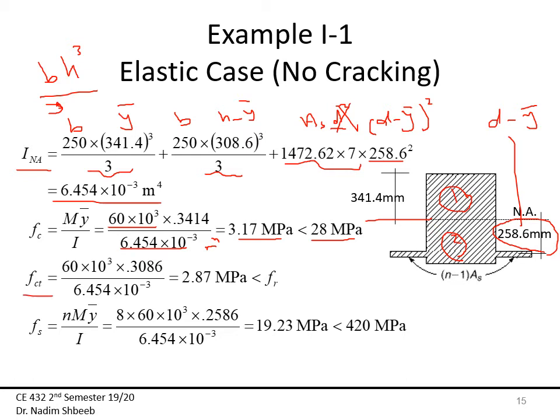Now I'm going to calculate the tension stress, and that's simply again the moment times the distance h minus y bar, which is this distance right here. So this is simply h minus y bar, this term.